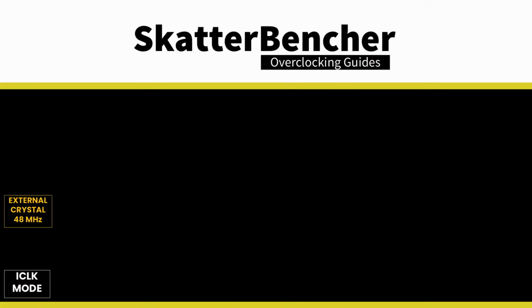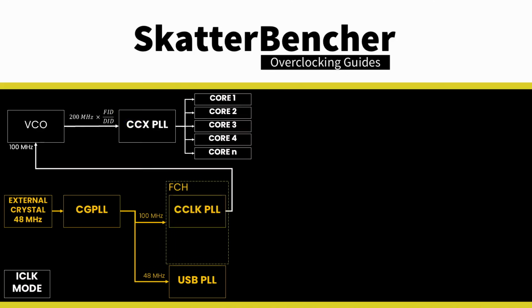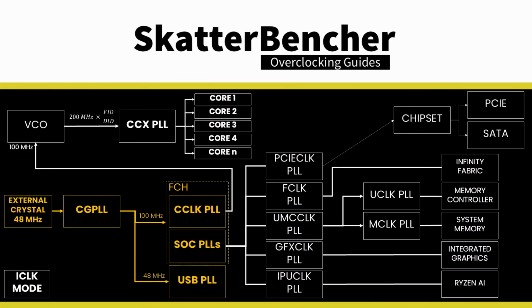The standard Granite Ridge platform has a 48 MHz crystal input to the integrated CGPLL clock generator. The CGPLL then generates a 48 MHz clock for the USB PLL and a 100 MHz reference clock for the FCH, which contains the CCLK PLL for the CPU cores and several SoC PLLs. In addition to the standard internal CGPLL, Granite Ridge supports up to two external clock modes. They're called eClock 0 mode and eClock 1 mode.